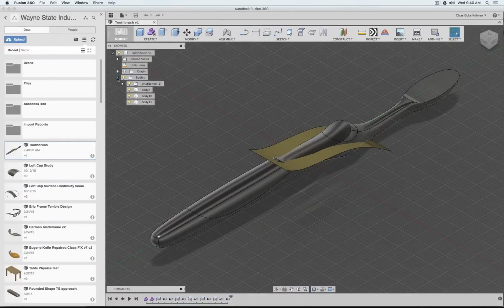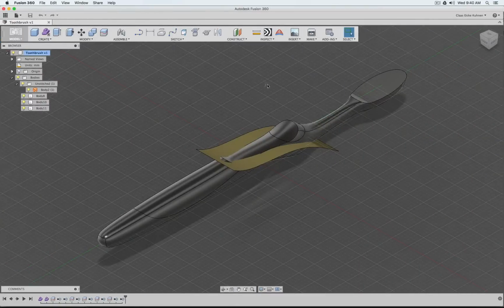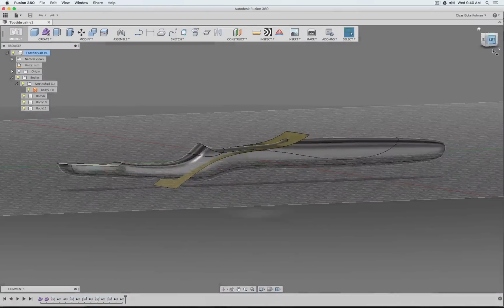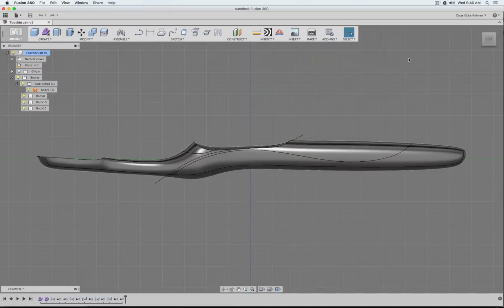Let's see if my workaround worked. And there it is. There's the stitched part, the object that wasn't visible. Knowing that bug, I knew that I just needed to save the file, and then when Fusion refreshes the cache data, it will show up.